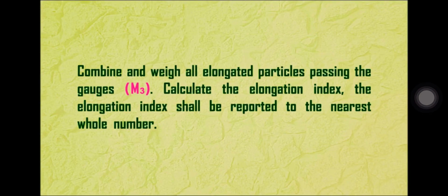Combine and weigh all elongated particles passing the gauge, M3. Calculate the elongation index. The elongation index shall be reported to the nearest whole number.